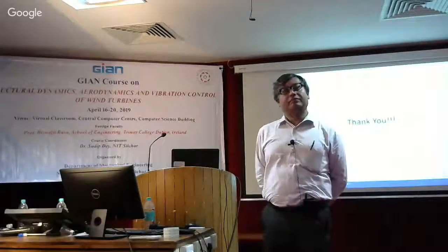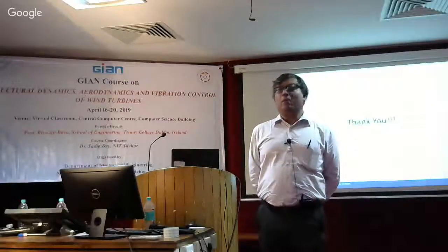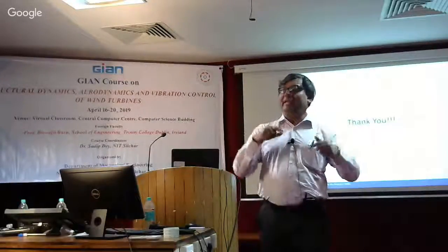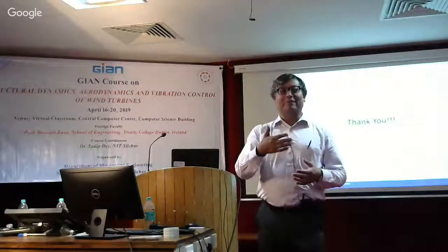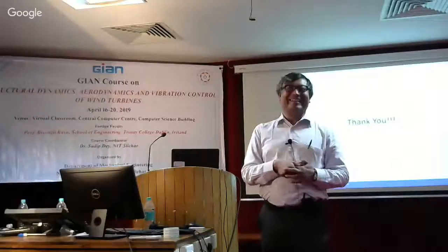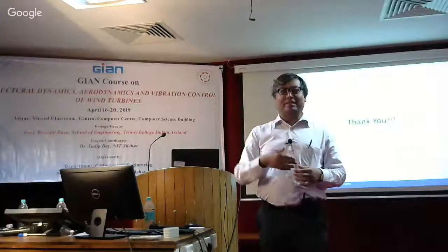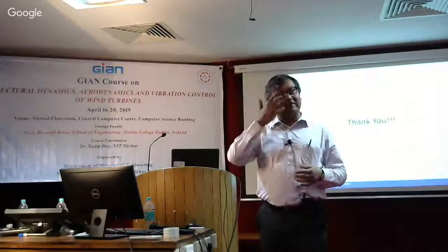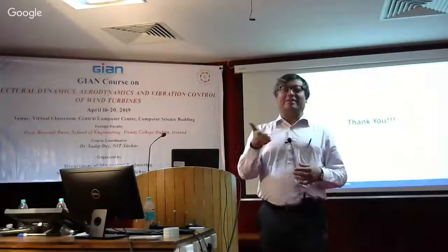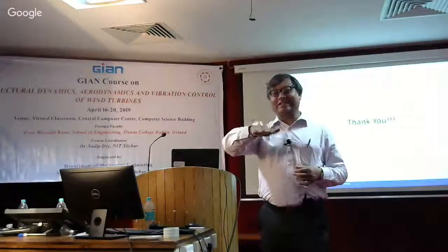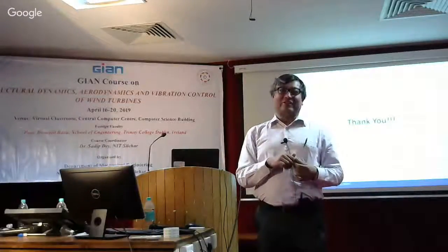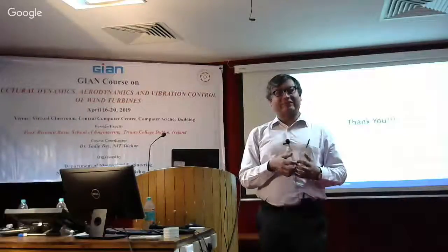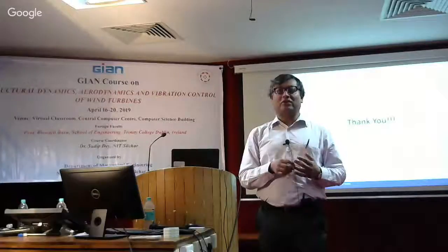Will pitch control actually not increase the power? No, because as I said right at the beginning, we don't need more power. In fact, the problem is that we have too much power, because you don't have to operate beyond 15 meters per second anyway. That's why you saturate it. So pitch control has a significant role in saving the generator from getting a power cut. If you don't use pitch control, you will also get reduced power because of vibration. The vibration will naturally reduce power generation.